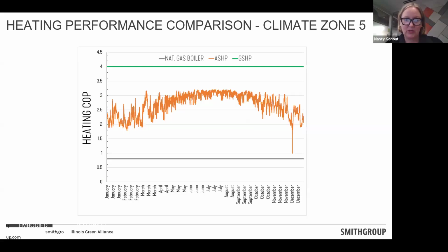We hear the term heat pump all the time, and sometimes we can buy condensing units for our home air conditioning that have heat pumps. They reverse the refrigeration cycle, but they struggle because as the outside air temperature drops, air source heat pumps' capacity drops off. What you see here in the graph in orange is how the coefficient of performance, or the efficiency, varies with outside air temperature. And not only does the efficiency vary, but the actual capacity of the equipment varies. And sometimes when it gets really cold, it doesn't work at all. So air source heat pumps can be a challenge for us.